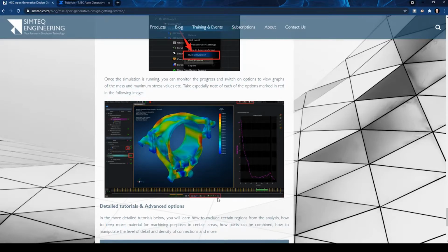And then at the bottom here, you have a number of options as well, with the important one to note is the last one, which actually gives you the opportunity to export an STL file of the current or any iteration over here. So not only the current and active or last resolved iteration, you can literally take any of these iterations, select it, that iteration will display on the screen, and you can export the STL. You can export it for use later as a new design domain or for any other purpose that suits your needs.